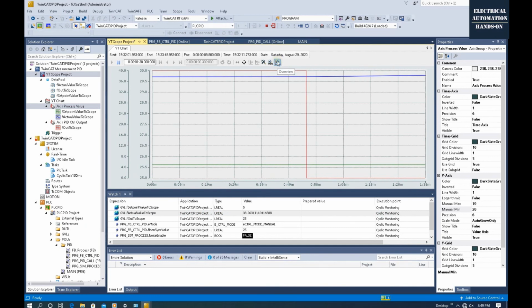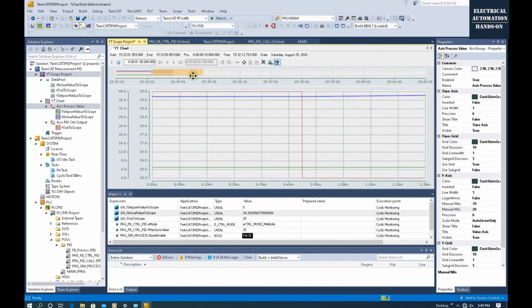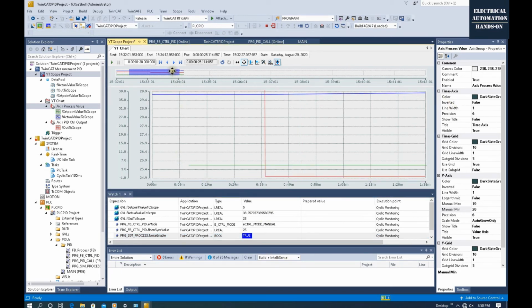And meantime, we can click this overview, so we can drag this monitor area if you monitor this process change online. Because the temperature is changing very slowly, it's hard to see the change now. But if we enable the noise, we will see the difference. For example, in the watch table, we enable the noise, prepare the true, and write the noise. After I enable the noise, this process value includes the noise, and we will see it's changing now.